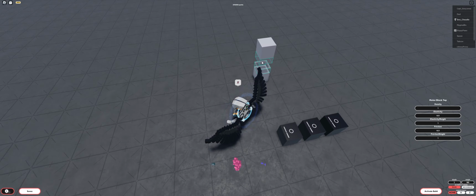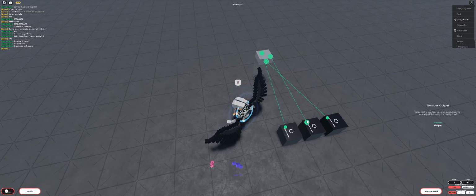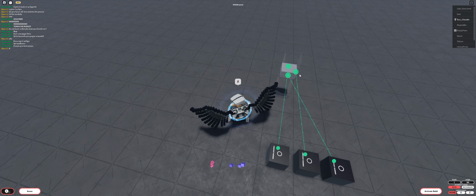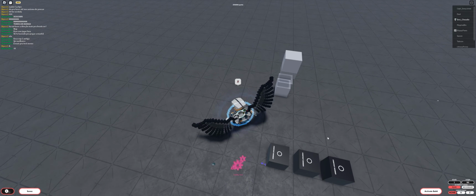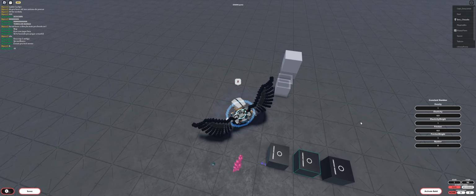Then on our second block, you'll notice in the logic that we have the acceleration. This is a very important value. We have to set this, otherwise the motor will not work. This is something that many people forget. The acceleration is simply how fast the motor gets up to the desired speed that you have set. It will never instantly go to that speed. So in this case, I'm going to just set this to 4.